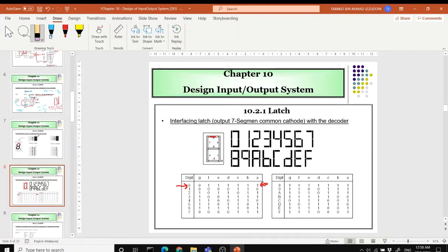Okay, let me show you another example so you can see it clearer. Let's say we're going to display number 4 on top of the 7 segment display. How are we going to do that? You look at this here, you set A as 0, so this LED is not lit up, but you put B as high, so this will be lit up.